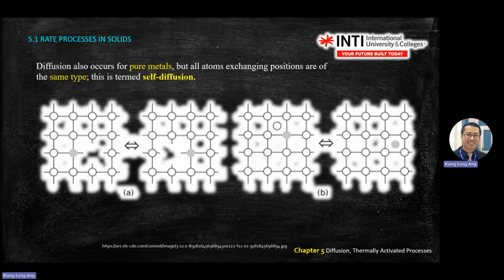Okay, so this is a defect. There's a hole there. This is a point defect. So the gray atom will move to the left, move to the right, and this one can move. The atom on the top here can come and replace this one, and this one can be pulled out from its location and then arrive at this location. This is called self-diffusion. Okay.